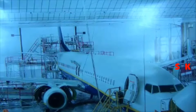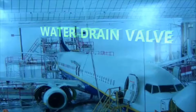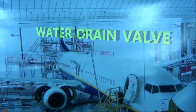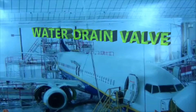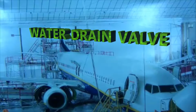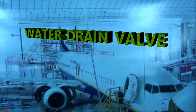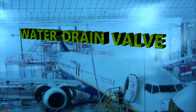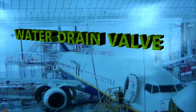All right, because I mentioned the installation of the water drain valve. The water drain valve, like I mentioned earlier, and we know what it's for, but that's just one example of one of those items, or parts, that is actually important to pay attention to. Because those water drain valves can also be a source of ignition in that tank. So you want to be very careful with the handling of water drain valves and making sure there's no damage or wear to those things.